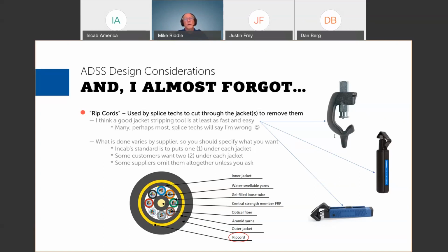And it doesn't work that way. An electrical engineer will understand what's wrong with that thinking, but the ground doesn't actually make the voltage go literally to zero. And so at least one utility actually did that and had a couple of its splice techs get injured during the splicing process because they thought you just had to ground it and then you're done. And no, it doesn't work that way.